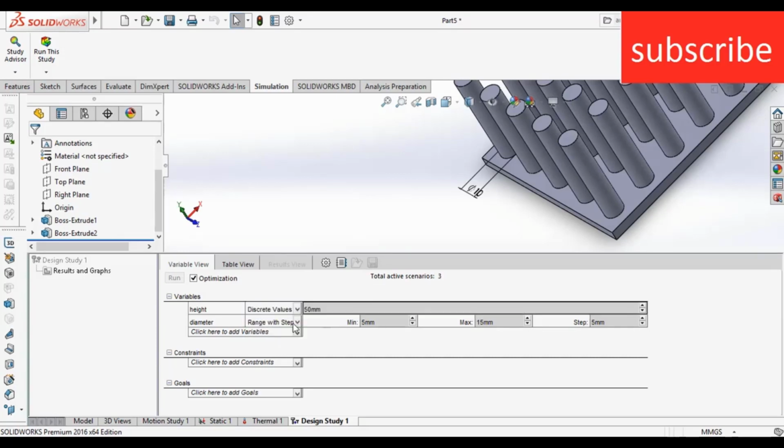Discrete value is basically, when you click on discrete value, it asks you to enter numbers separated by, for example, commas. You say you want a height of 50 mm, and after that a height of 10 mm, 15 mm. So you enter the values at which you want the simulation. When you select range with step, you get fixed step values and you get the result. But in this case, you enter individual height values at which you want to calculate.